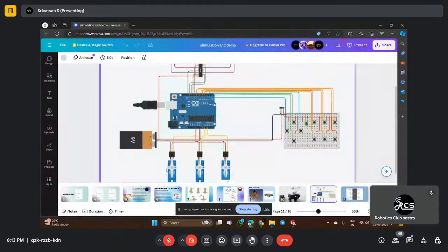Now you will have a doubt that there are three servos. What are the uses of these three servos, right? This servo is used as a base motor, which is used to move the connecting rod of the manipulator, and then this is the intermediate servo motor, which is used for the offset movement of the gripper, and then this third motor is used for the open close movement of the gripper, right? Hope you all have a clear understanding of these three motors.